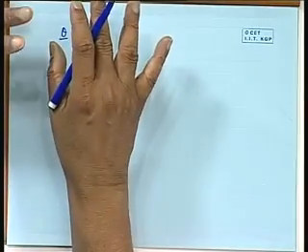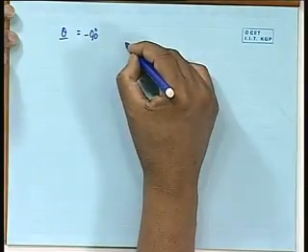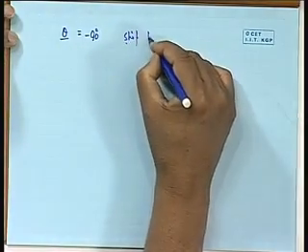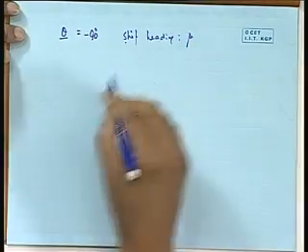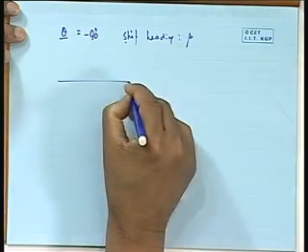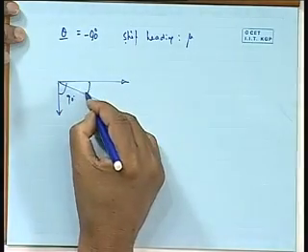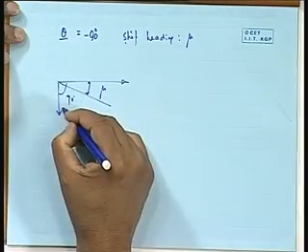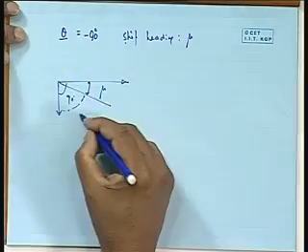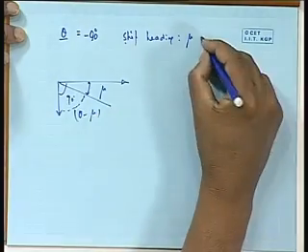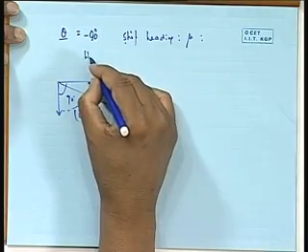So let me say we can go this way. Theta is the wave heading angle, and then the ship heading. Now you see here, the ship heading angle is mu. Now here this is interesting. See, this is my x-axis. So my wave here is 90 degrees. This is the wave, and my ship heading angle is actually this, say mu. Therefore the relative angle becomes theta minus mu. So it becomes theta minus mu. This will tell me what my heading angle is with respect to the wave.